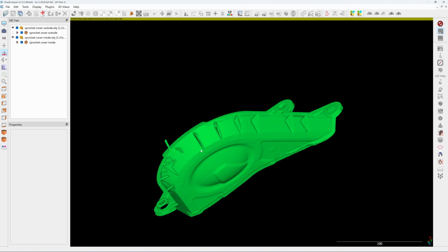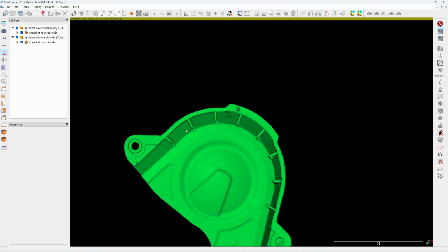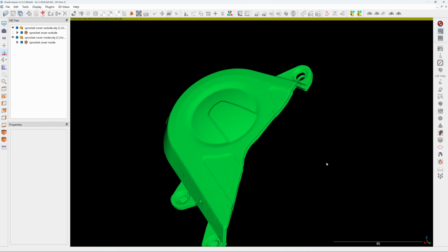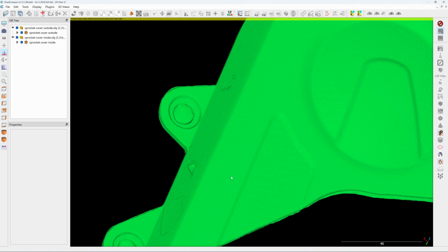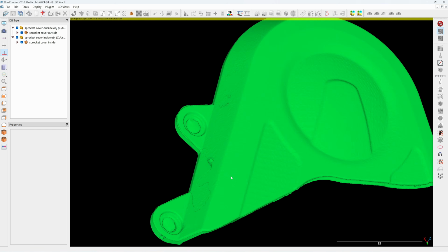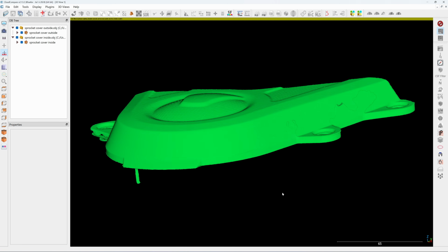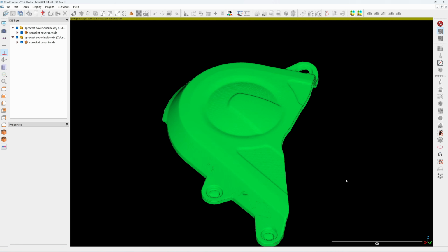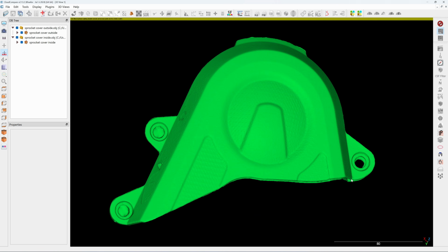And I recommend that for a pocket and crevice like this, you use a spray to get a more complete surface. So next step, I'm going to convert this into a point cloud. Because if you use a mesh for reversing in CAD, the mesh will consist of edges and faces. It will block you from seeing the edges and the wall. So the best practice for reversing is to use the point cloud. Most major CAD software can import the point cloud for reversing, for example SolidWorks, Inventor, and Rhino.